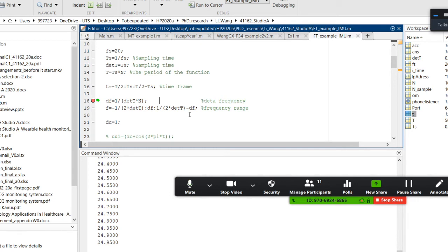If you observe an airplane take off and open your eyes every second, you will see it. But if you open your eyes only once every hour or every 2 hours, you cannot observe what happened in between. So you need to be fast enough. This is the sampling frequency. If something changes at a frequency of, for example, 10 hertz, you need at least 20 hertz, double the speed, to observe it.